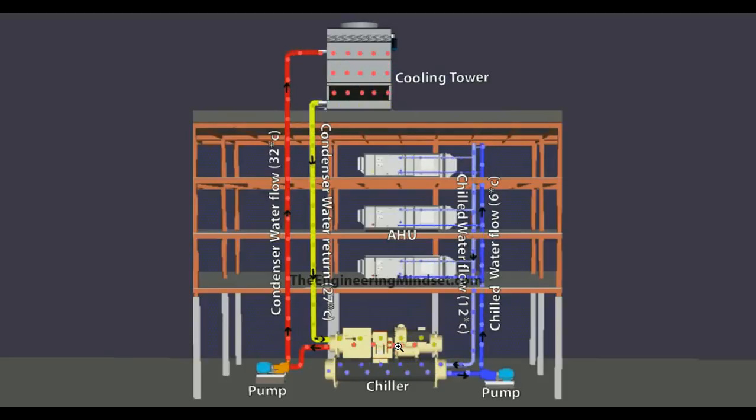The chilled water system in this example is a central system, so it's got to a point where having small air conditioning units on each floor is not going to be sufficient to provide the cooling that you need. So it becomes economical to install this large central plant system to produce that chilled water.